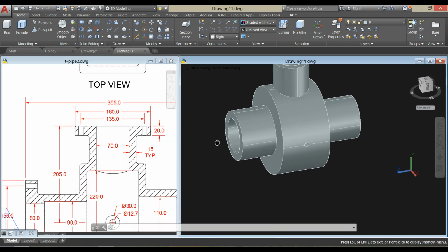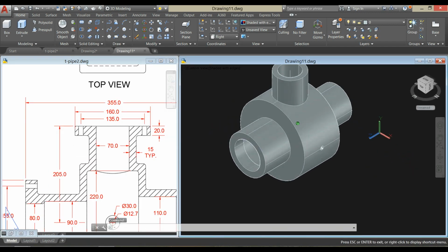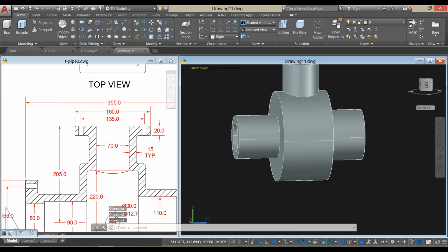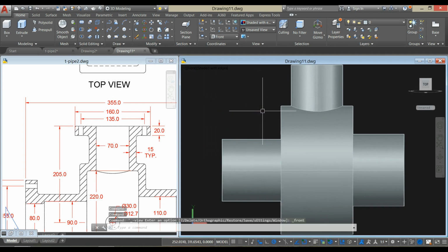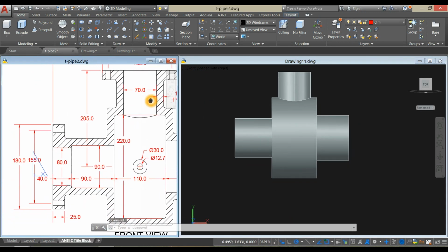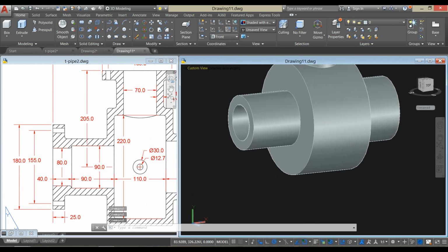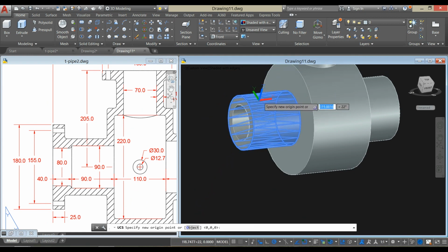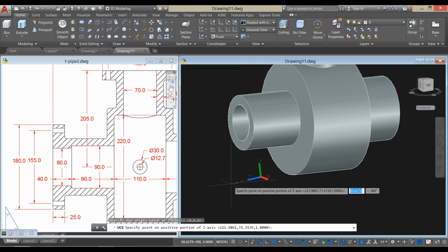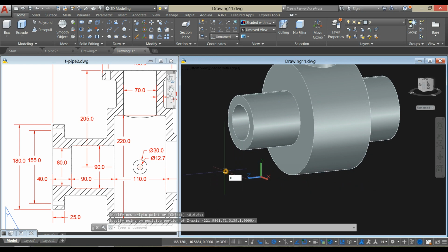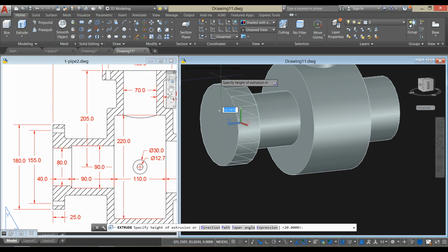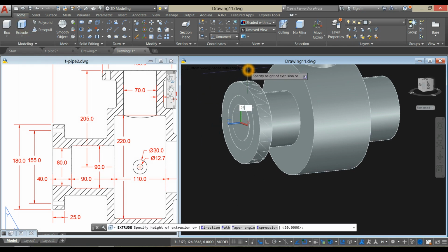and create the flanges. So let's start on this side first. To bring this drawing to front view. And attach the flange here. So I'm going to change the direction of my Z parallel to the direction of this cylinder. So C for circle. Locate center and enter D for diameter option and enter 180. Extrude this one towards the center for 25 units.